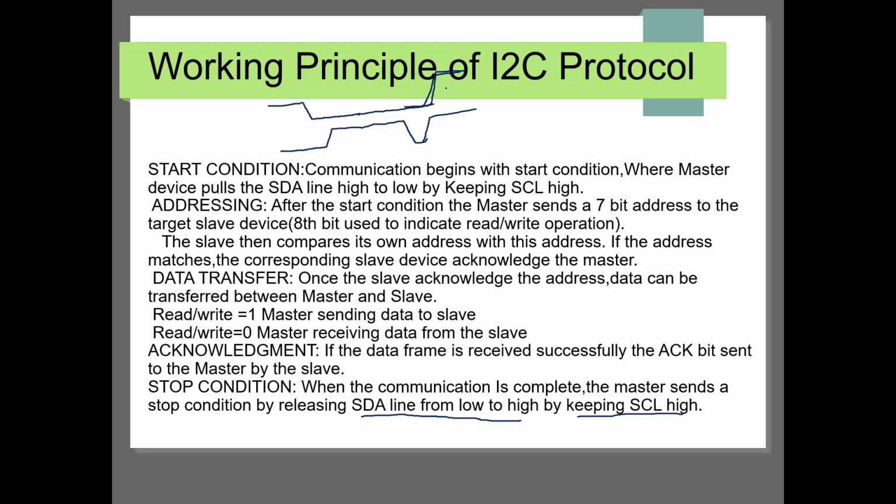After pulling the SDA line from high to low, the clock is set. Before that, the clock should be going low, and after that it goes high. We don't know how much time it is maintained high or low. So that is the stop condition.